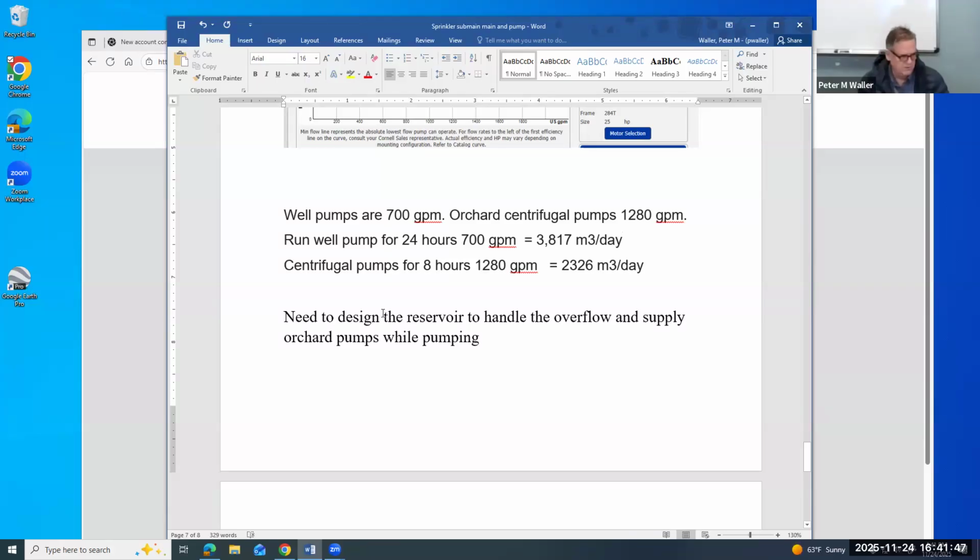You might have it be 2 meters deep or 3 meters deep. You need to have, I think, 5-to-1 side slopes, because cows or people could get in the reservoir and they need to be able to walk out. Chapter 20 talks more about reservoir design. There are certain ends that maybe have less or more slope. But anyway, now you need to design your reservoir.